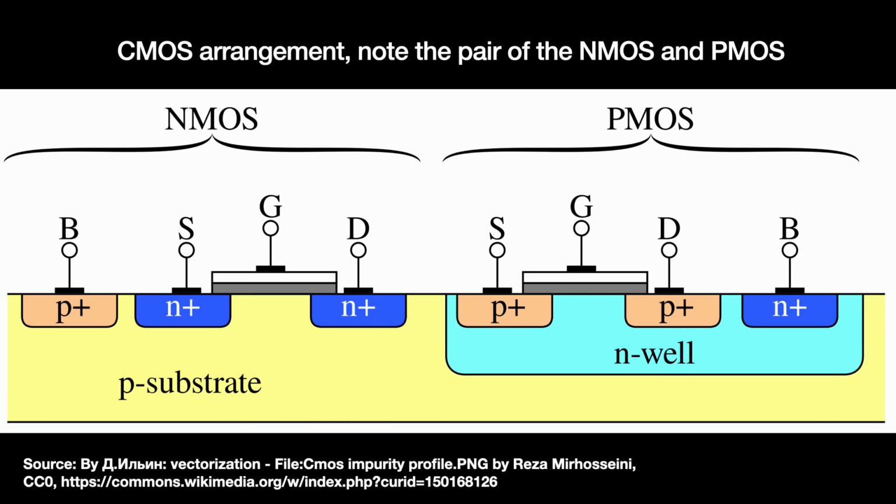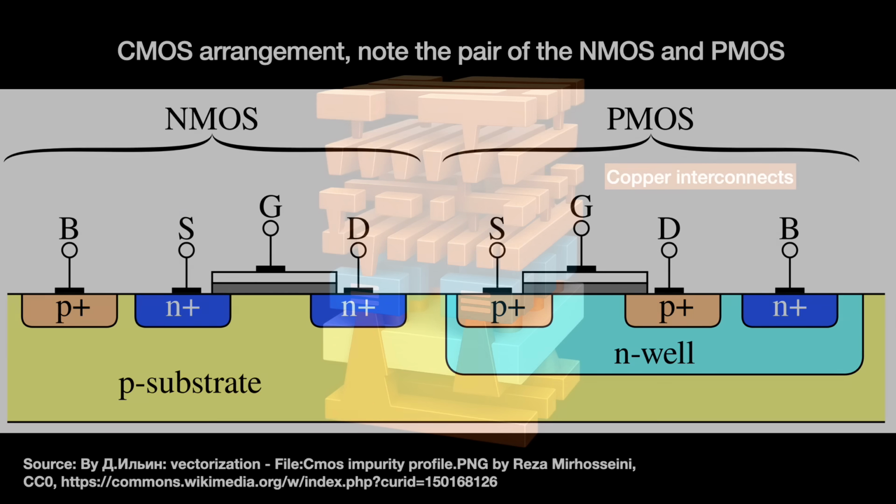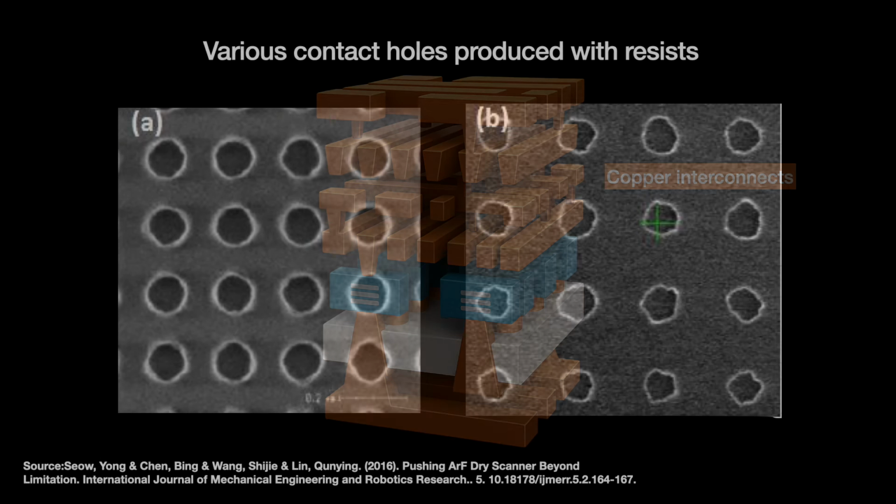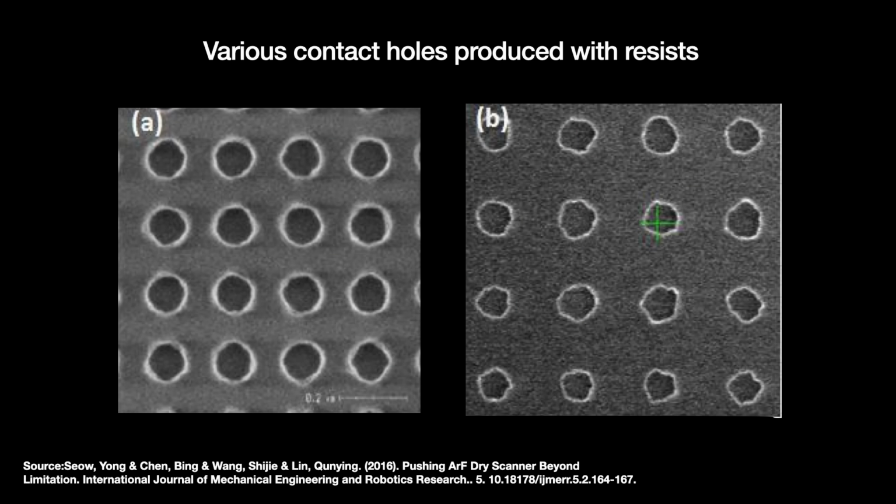The transistors are wired up to metal interconnects embedded in layers on top of them. These layers are called metal layers because the interconnects are metal. The metal wires go down and make electrical connections with the transistor itself at specific points called contacts. It is a significant challenge of device scaling because the contacts shrink with the device.